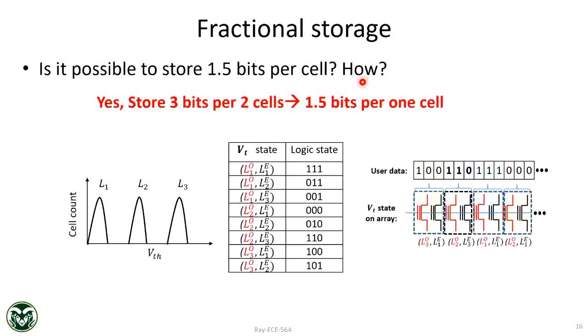So I hope by this time you understood how we store multiple logical bits on the same set of physical cells, right? We are not doing anything in the hardware. Hardware is exactly the same. Whether you are using an SLC memory or a QLC memory, your hardware looks exactly the same. Maybe the charge pumps will be a little bit more powerful for QLC because you have to go to higher voltage. Maybe your programming algorithm will be a little bit different, but from a pure silicon point of view, it is exactly the same.